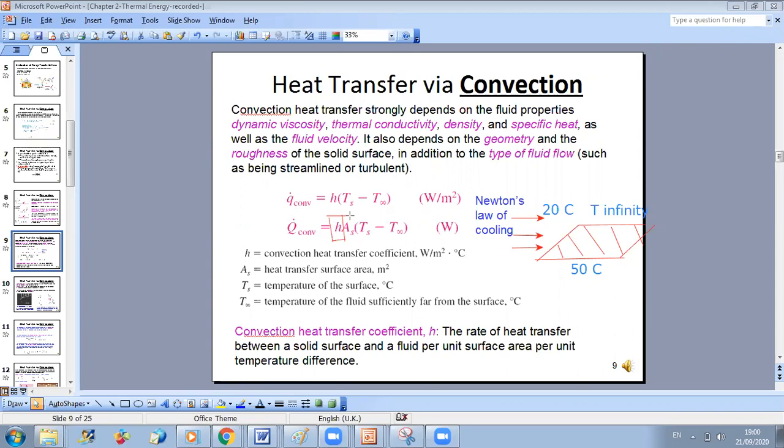Then you need to know if your flow is, let's say, turbulent or laminar. Do you know how we determine if a flow is laminar or turbulent? First, do you know what is a laminar flow or turbulent flow? Reynolds number? Yes, very good. So look, if you look at a flow and you can see clear streamlines that are smooth, so you have a flow that is called laminar flow. It is very ordered, it's moving along streamlines that are parallel to each other. This is called laminar streamlined flow.